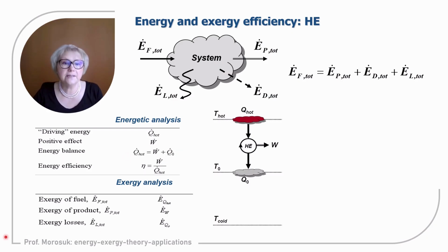Now, exergy analysis. Exergy of fuel is the exergy transferred to the system. Exergy of the product for a power generation system, a heat engine, is definitely the work generated by the system, and the exergy transferred to the environment is the term of exergy losses.